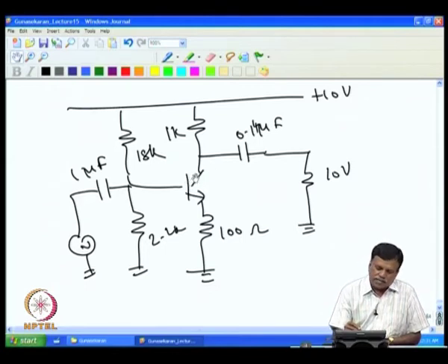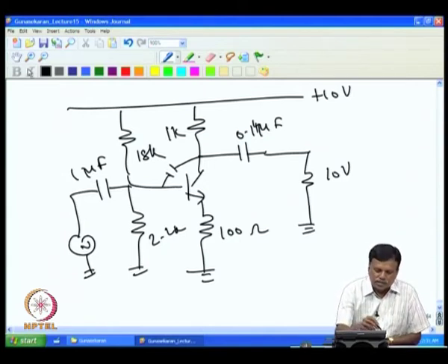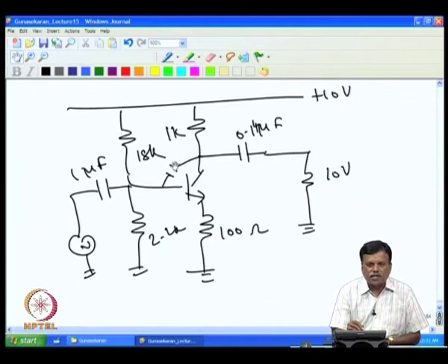In the actual case, we have to consider there is a capacitance across this, and because of this capacitor, the output voltage is partially fed back to this, which applies a voltage here, reduces the voltage at this point, and that also reduces the voltage at this point. But this capacitor effect is not significant at 1 kilohertz. So, one need not worry about that.